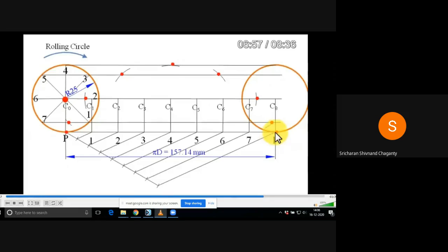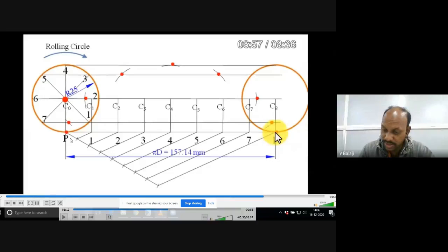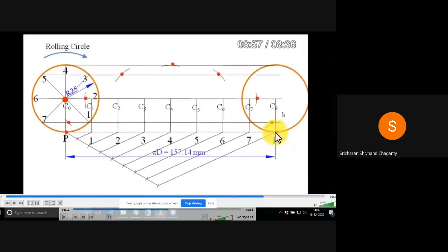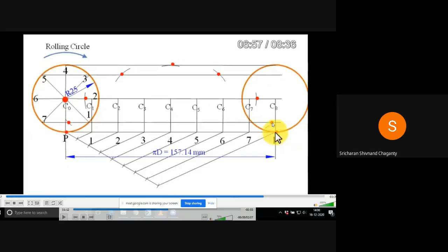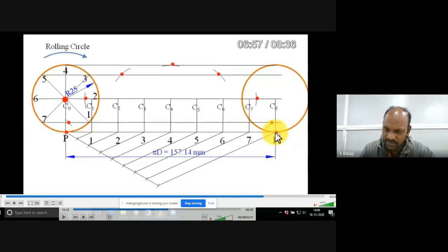Yes, sir. And from C8 should be the last arc, right, sir? See? No. C8, it is given extra. You don't take C8, okay? Last is C7. C7, okay. If you take the compass here, C7, you cut this red point I am showing you here, small arc here, okay? From C7, if you cut the seventh line, where? Again, a line common to 1 and 7 only, okay? So this is the last arc. So anyway, the point comes to its original position here, okay?